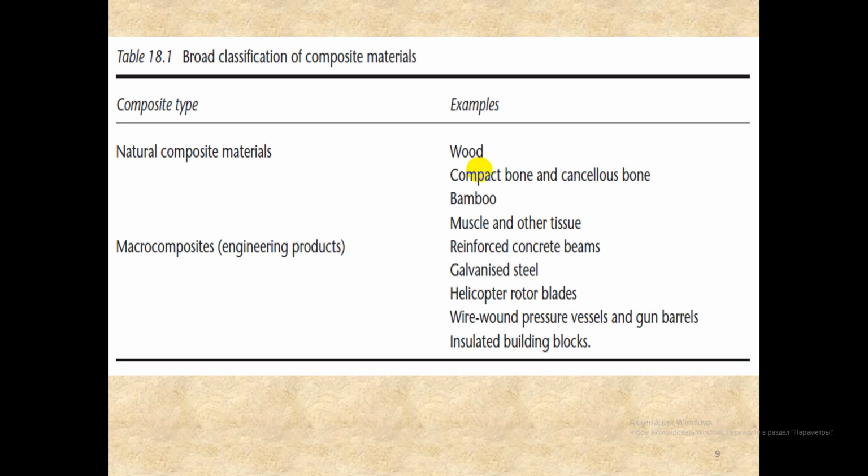The second material can be in the form of short fiber randomly arranged, in the form of particulate, spheres, plates, ellipsoids, etc. in the matrix, as lamellar structure of alternate layers of the materials, or as skeletal or interpenetrating networks.